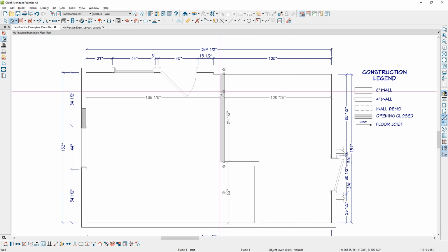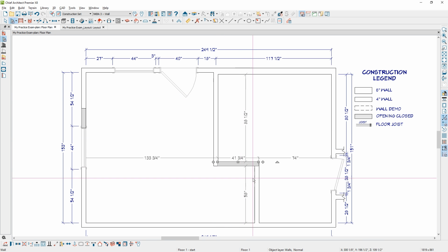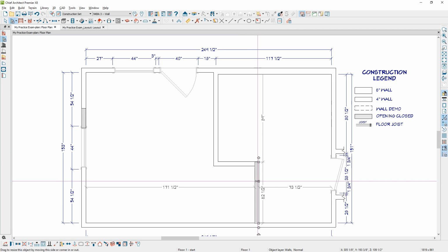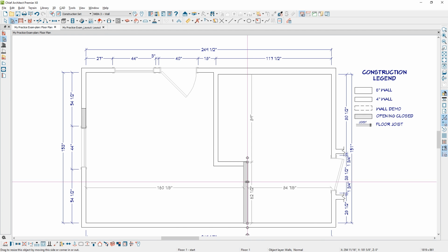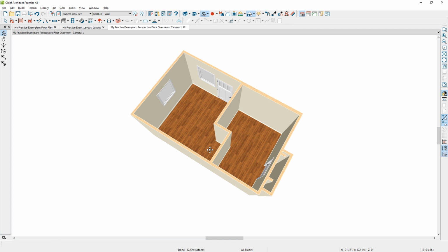In this case, I want to make sure that this aligns up here to this wall. Once I've got this set, I'm simply going to trace over these with a CAD box, and then delete these walls because I don't want to see them in the design. I don't want to make them invisible in Chief Architect, because that gives me a room definition, and it may make it more difficult to place objects over a wall or set ceiling heights in a particular way.